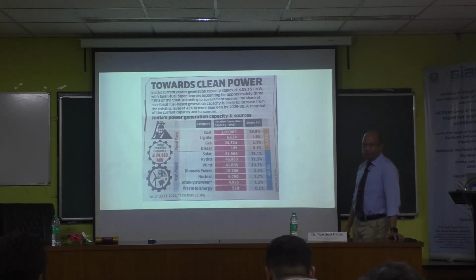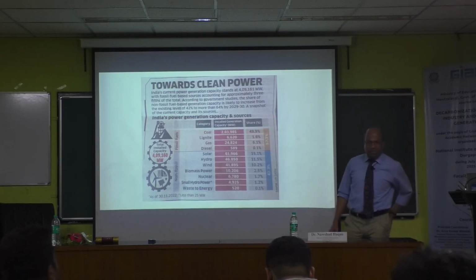The usage of electricity is in units like million units or kilowatt hour. So what we do, I told the people to put another column and see the running hours per year. Maybe a coal-fired power plant runs 8,000 hours. This is the capacity factor. What's the typical capacity factor for your plants?